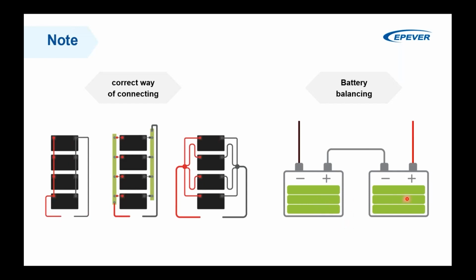You can disconnect the batteries when they are fully charged and check if they have the same voltages. If there is a voltage difference higher than, for example, 0.2 or 0.3 volts between them, this is a problem, and you need to think about it and correct the way that they are being charged.